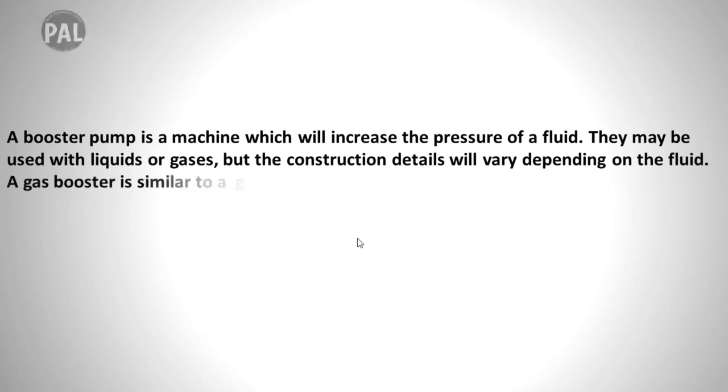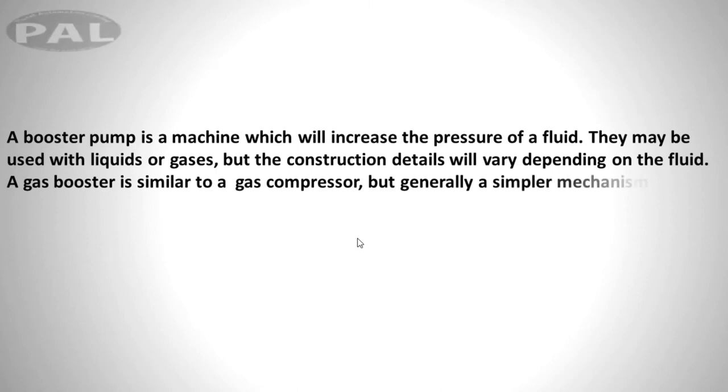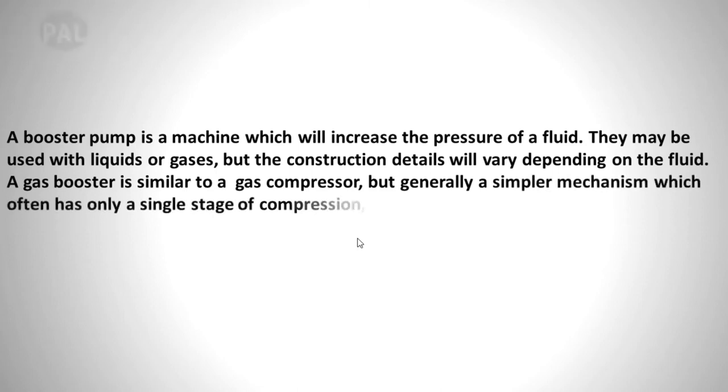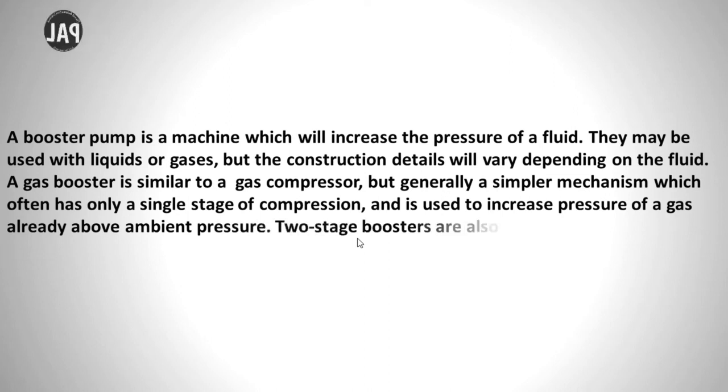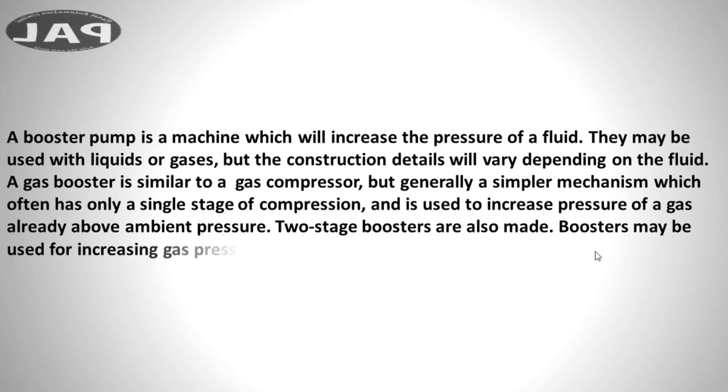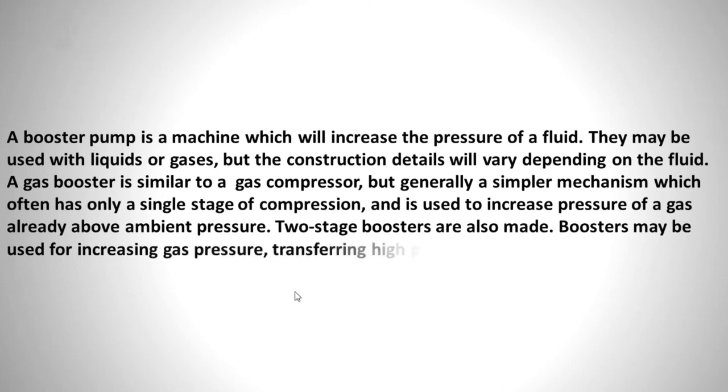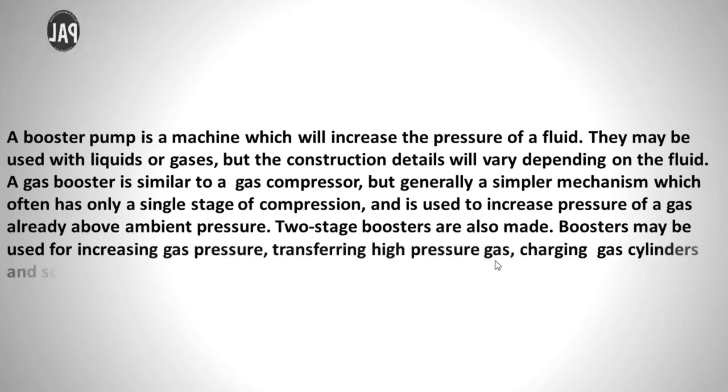A gas booster is similar to a gas compressor, but generally a simpler mechanism, which often has only a single stage of compression and is used to increase the pressure of a gas already above ambient pressure. Two-stage boosters are also made. Boosters may be used for increasing gas pressure, transferring high pressure gas, charging gas cylinders,